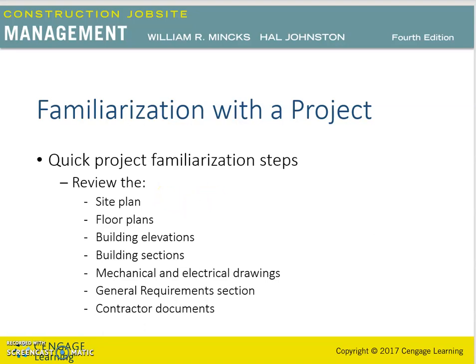So for example, first of all, the site plan should be reviewed. So become familiar with the relationship of the structure to the rest of the site, note the site limitations and access, as well as adjoining property and the relationship of the project to the adjoining property. Floor plans should be reviewed, so the two-dimensional size of the building and its floor should be determined.